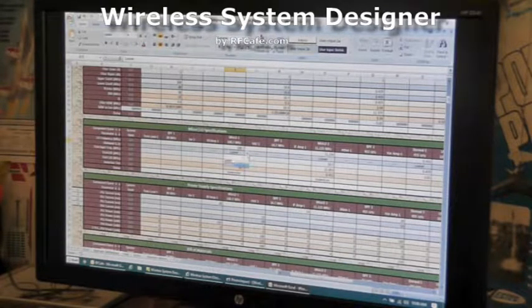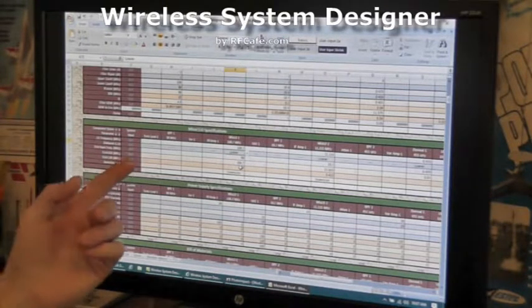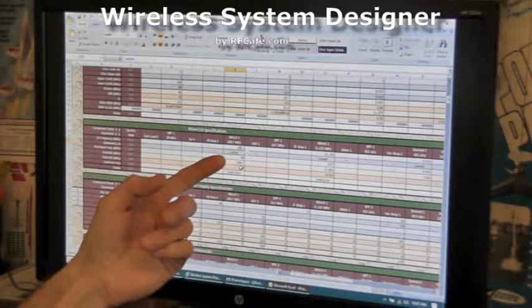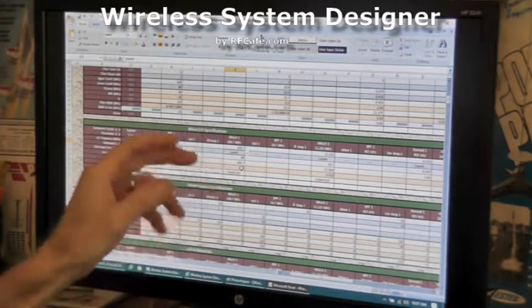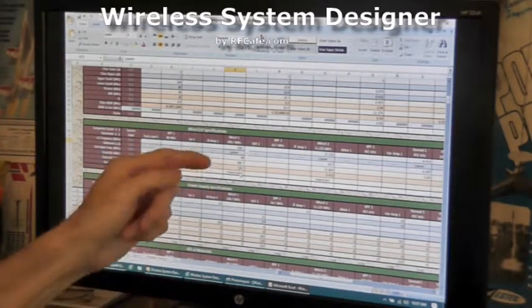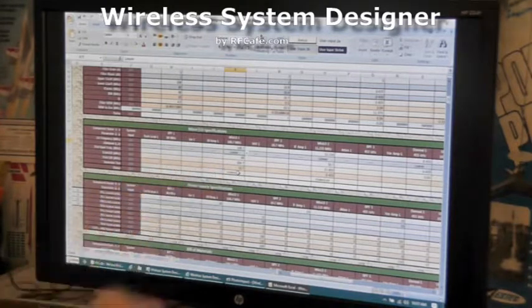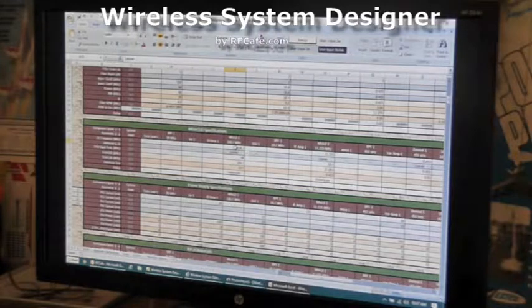If you have a frequency specified and you don't check a sideband, I give you a sideband flag here just so you remember to actually set one. You can put in a trial frequency just for use within this part of the spreadsheet, and it calculates what the upper and lower sidebands are for you relative to that LO frequency, again, just for your use here, so you can make sure you've got your numbers right.